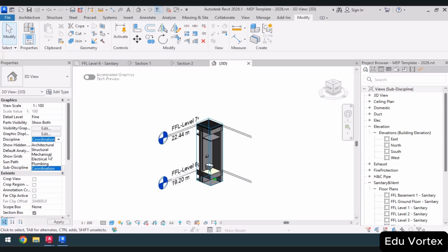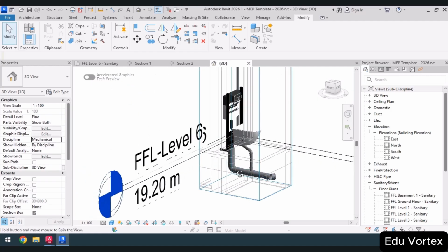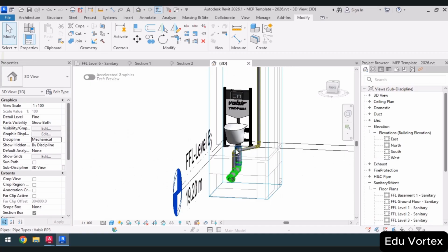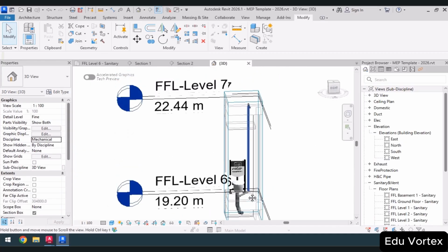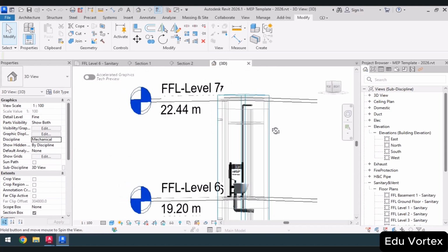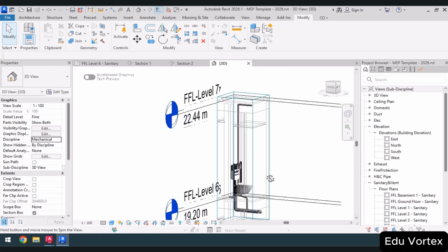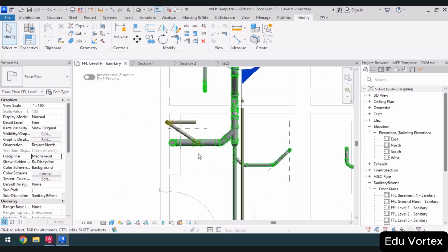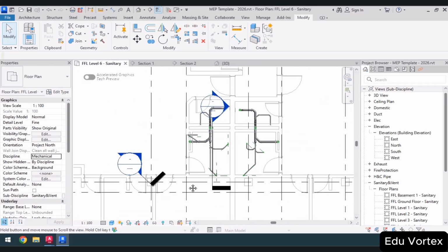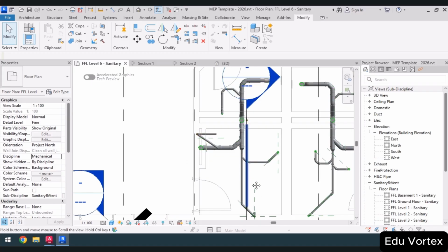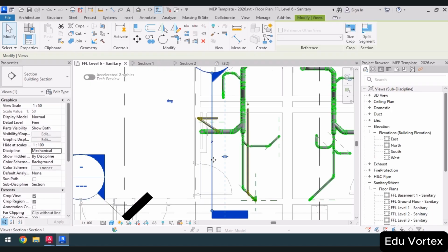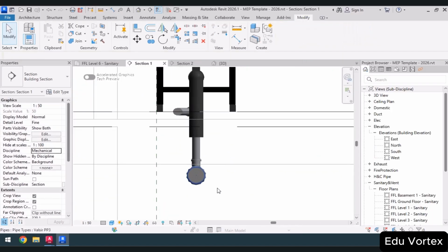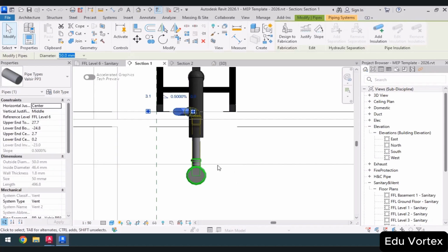It's better to set this section box to mechanical mode. I mentioned earlier that it should be from 0 height, but now I need to bring it lower so that it comes below the ceiling. It has come up into the wall at the height I specified. Let's adjust the height of our vent in this section. I can select this section and right click to go to view. This is our ceiling, and you can see how far down the vent can go.